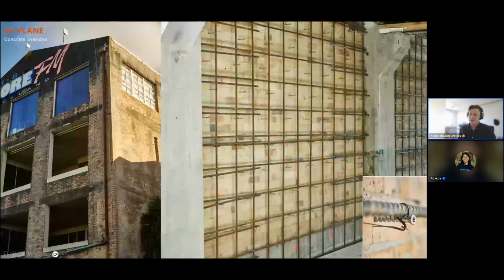In-plane shear strengthening. This is being done on a couple of high-profile, high-value commercial projects in Australia at the moment that I'm aware of. Quite an effective solution for increasing the strength of a masonry wall in plane. One of the key considerations of this technique is if you have quite dense reinforcing, large gauge bars closely spaced, you do need to be careful that you're not creating voids in between the masonry and the bars, essentially. That's not too difficult for an experienced contractor with the correct vibration tools to ensure they're doing it correctly.